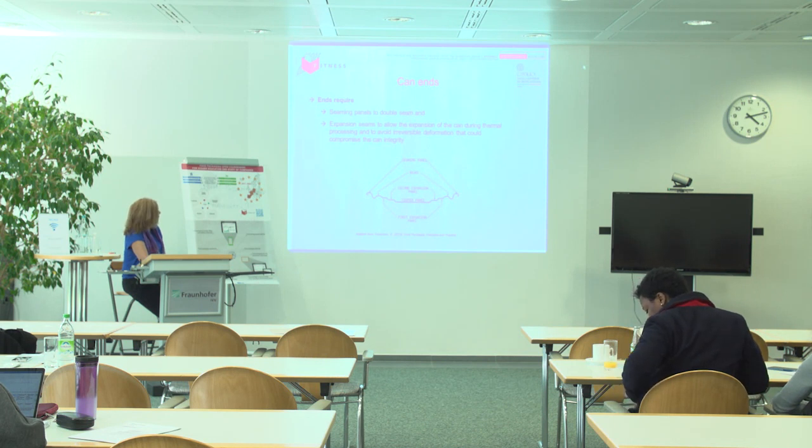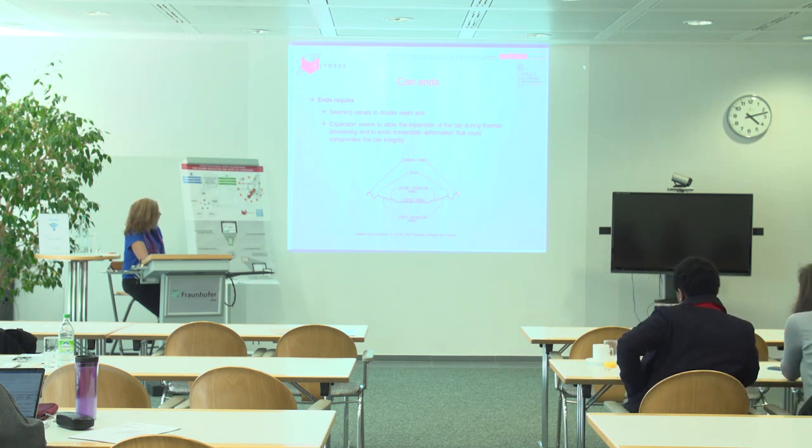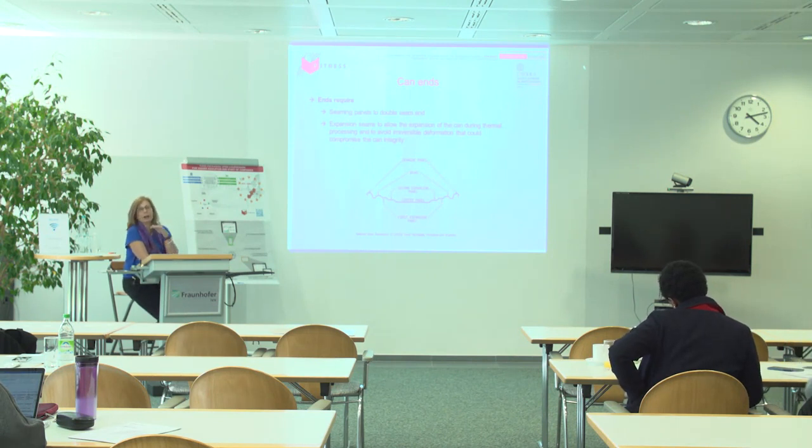On the can ends, we notice that the ends are not flat, we have several expansion panels, like here, and these expansions are to allow the expansion of the can when the can is being processed. So when we are thermally treating the food inside the can, we have an increase in volume, an increase in pressure, so the can expands.